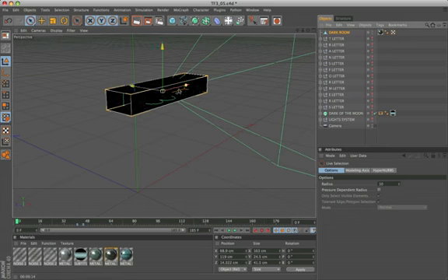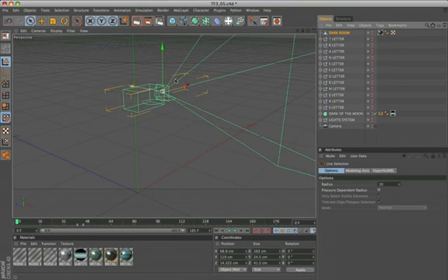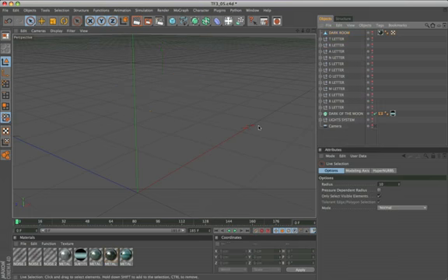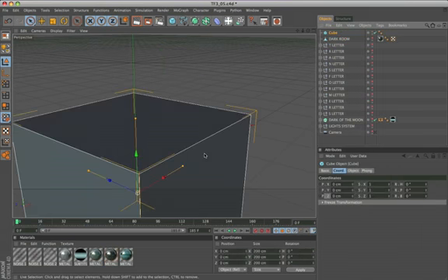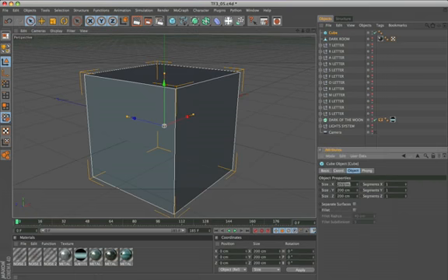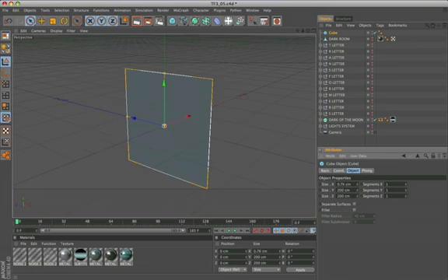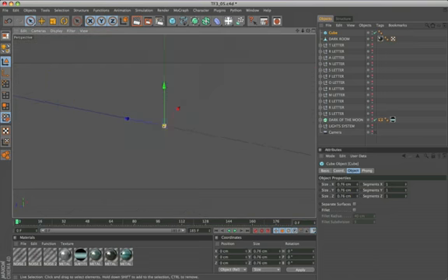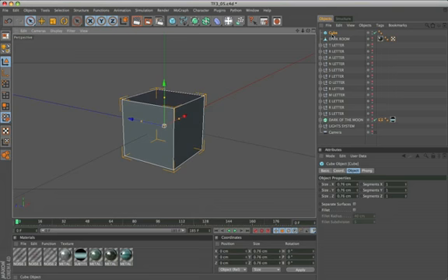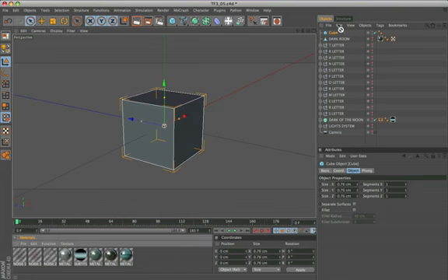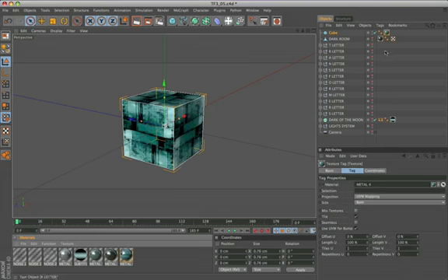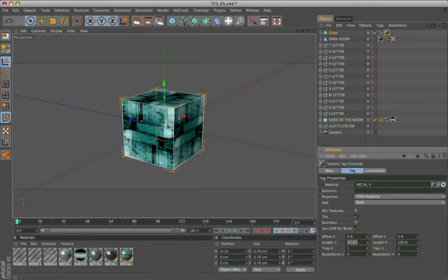Let's create the texture, to give a dark room with our high-tech style. Insert a new cube with a measure of 0.76. It is a very small cube for our scene. We apply the texture metal 4, with length U to 137 and length V to 50.